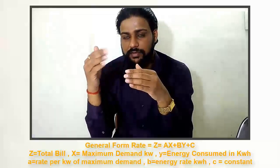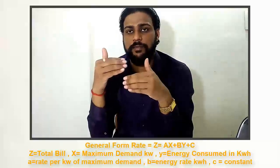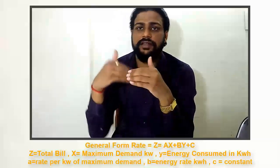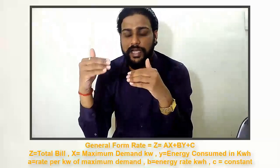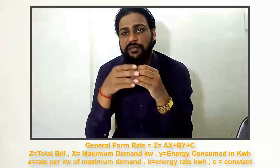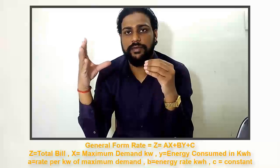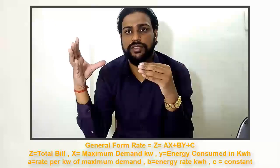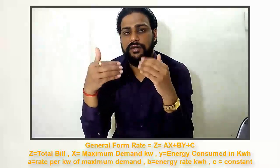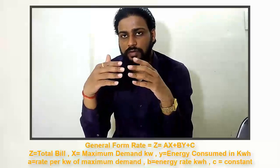And whenever it converts to steam, the pressure and the temperature of the water would be increasing. And whenever it is converted to high temperature and high pressure, this steam would be thrown on the turbine. It can be thrown through the nozzles, converting the high temperature and high pressure into steam at a high velocity. While it is working on the turbine blades, the pressure will again get reduced. So that's one point.